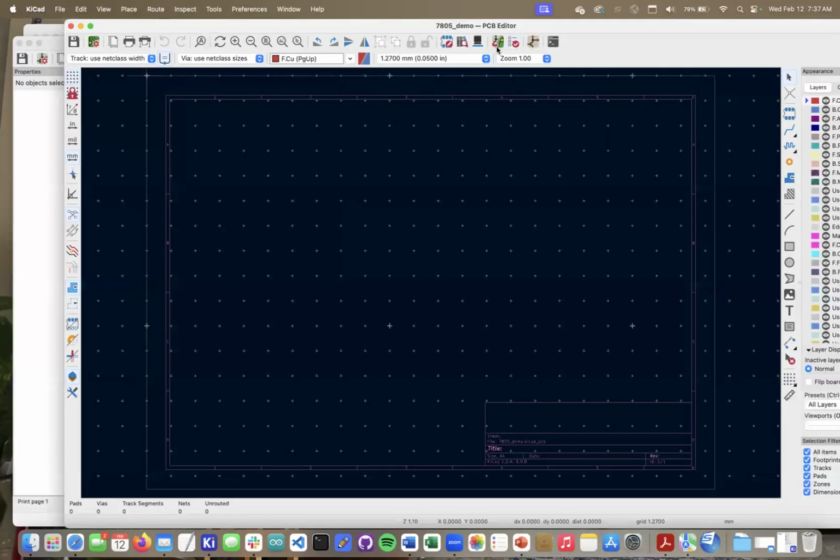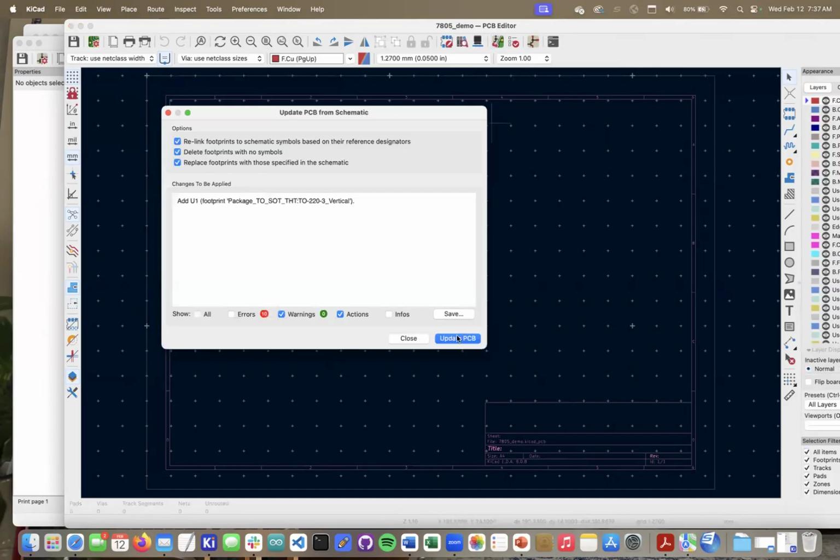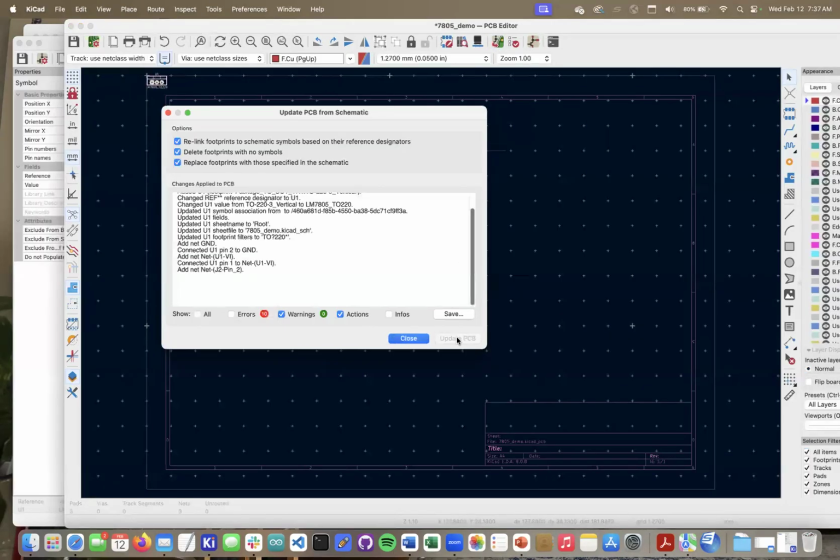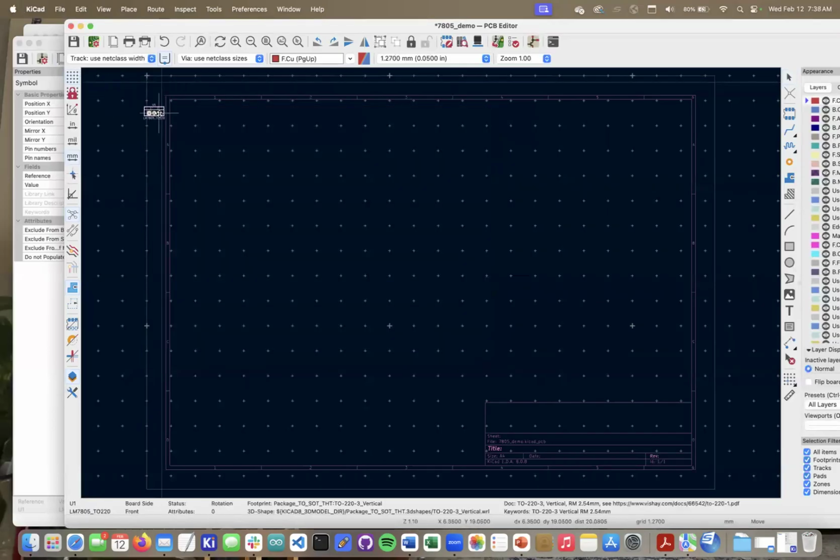And you can see I have up at the top menu bar here, let's just notice that this tan one is our schematic editor. The green one was the PCB editor, and here's one that shows an arrow between the tan one and the green one. That's going to pull the components from the schematic into the PCB editor. All right, and here it is all up here.